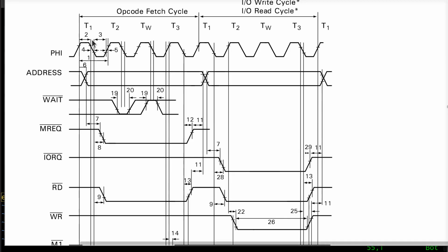Now it turns out, if we have to go through 2 cycles in a row, we need to make sure our state machine resets itself before it's needed again, right? So let's say there's 2 of these back to back. Technically, the Z80 CPU can't do 2 of these back to back. But if we had it set up to do memory transfers instead of I/O requests, it can do memory transfers back to back.